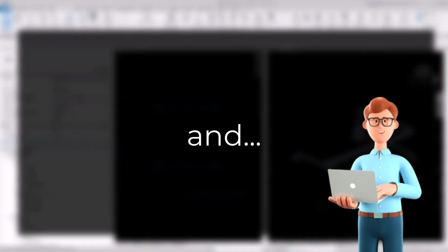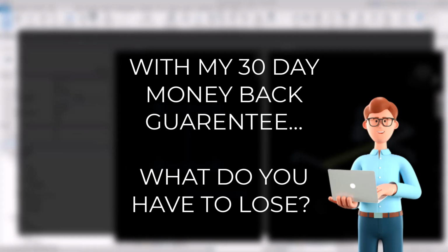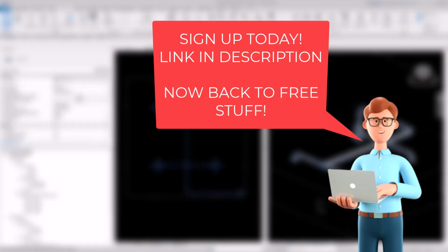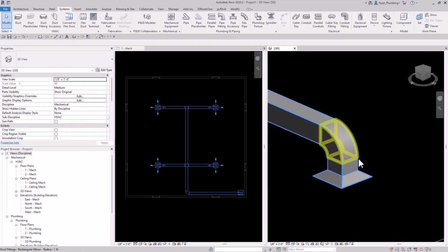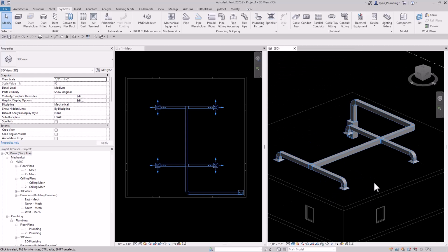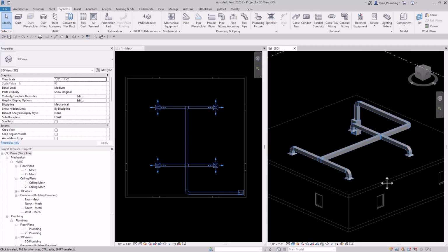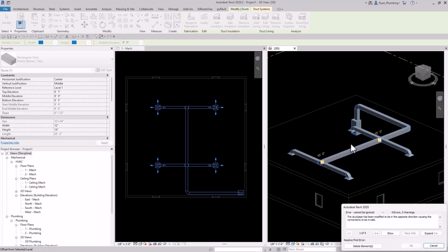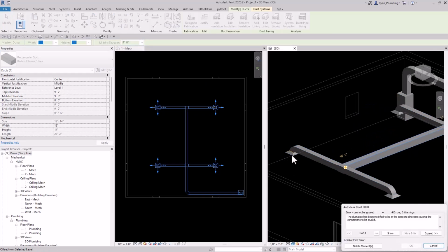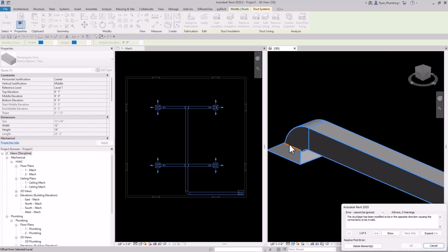So that was important because now what we can probably do is lower this duct a little further down. We want to lower it to a point where we still have a little bit of this duct so it doesn't break. Let me show you guys how to do that. There's a couple different ways you can manipulate duct elevations. You could just click on the piece of duct and change the elevation up here. So let's say I wanted to change it to 9 foot. I would click that up here. But again, we're getting some error messages saying, hey, you made it too low.